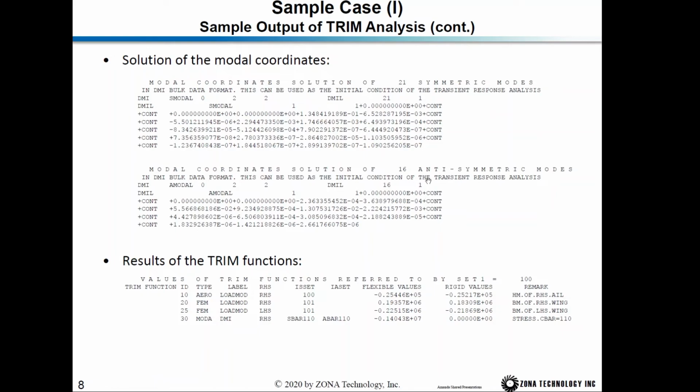And if you do the nonlinear flutter analysis or ejection loads analysis, because those analyses are nonlinear, the initial condition of the starting point must be specified. So in those two modules, you need to obtain the initial modal coordinate solution. So this output sometimes you need to cut and paste back to the ejection loads and nonlinear flutter analysis input file.